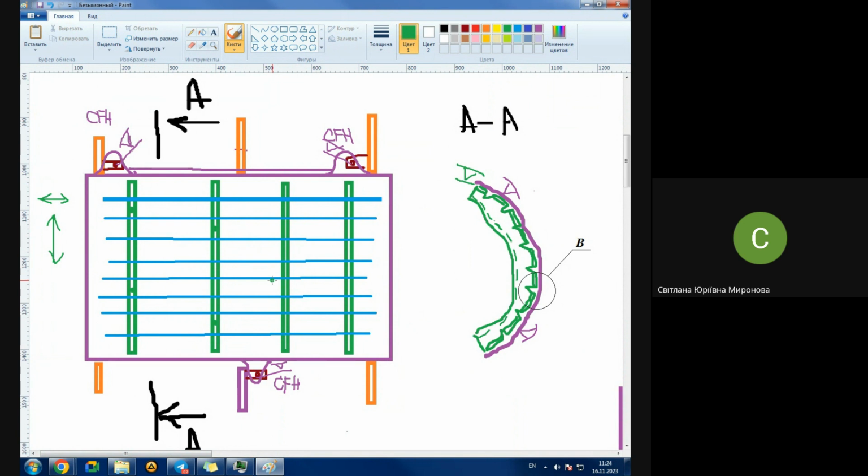To be frank, when it's a regular panel and all the frames are identical in shape, the lines of holes are also identical. Let it be, I did something like this. And now I need to show signs also, and type assembly hole, assembly hole. Look, is it enough to have a couple of assembly holes in this panel or not?